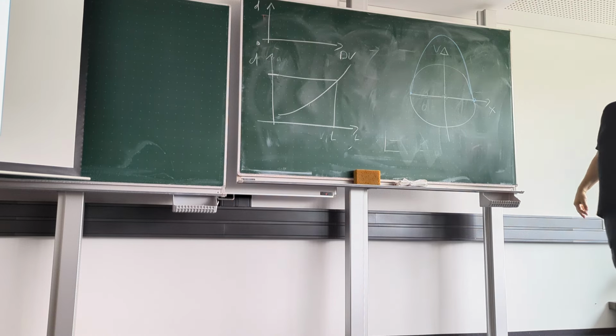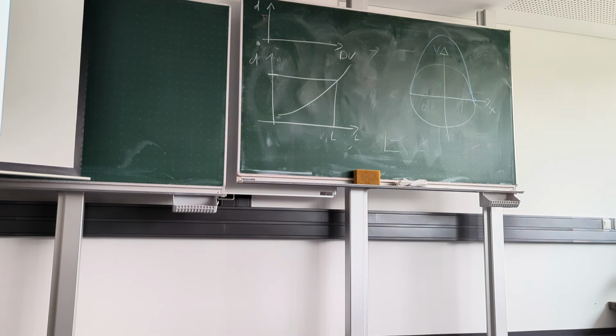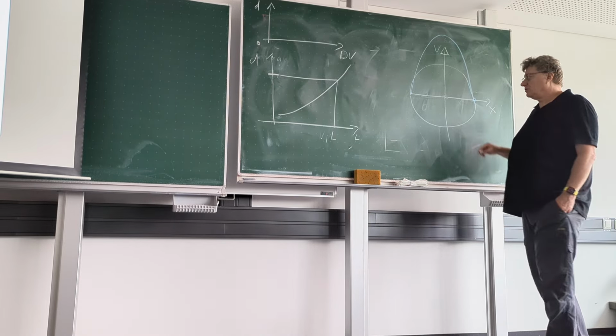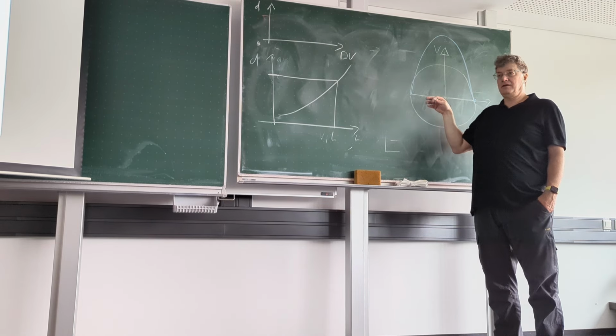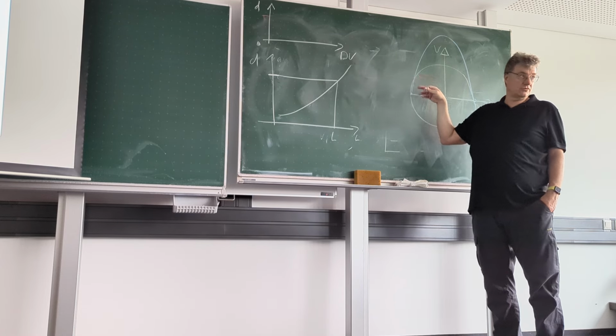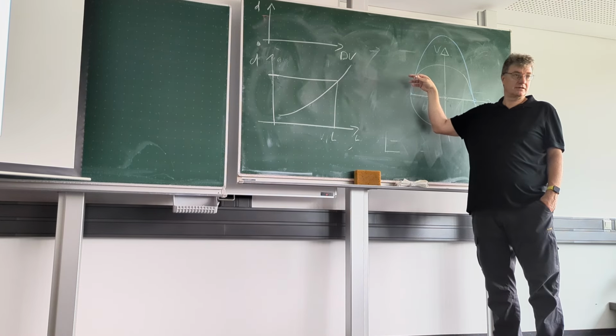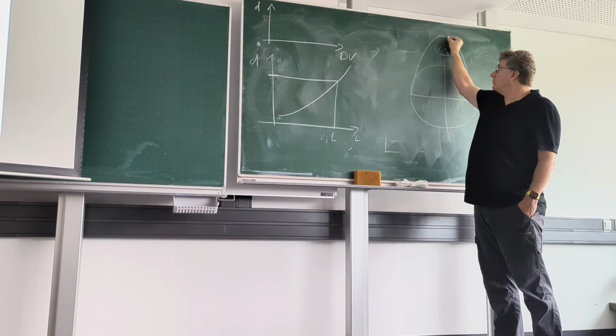That could be an idea. If you analyze a bit more, then you will come up that you need to have a fine mesh in those regions where the parameter velocity changes most, where you have the highest gradient. So here in the maximum it's almost flat.